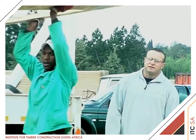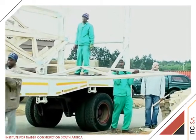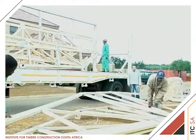Important to note when we deliver and stack these trusses on site is that when we get to the bigger span trusses, as we see being taken off the truck here, we generally require more hands to keep the truss level, and as a result not put additional stresses onto the nodes, which cause potential problems and could give us problems on site in erecting these trusses.